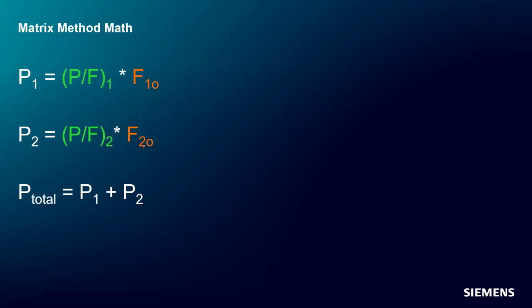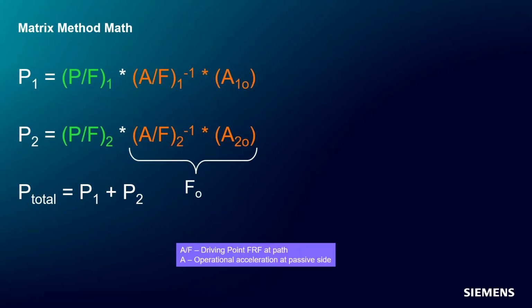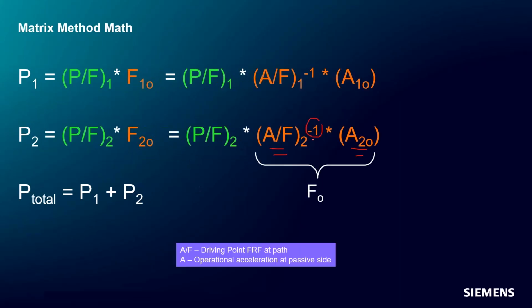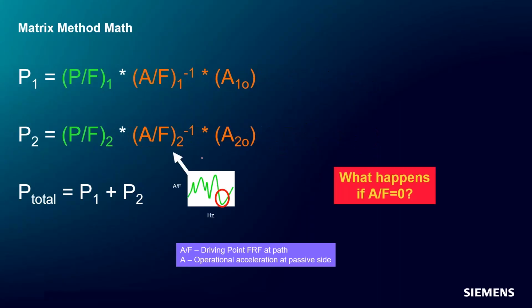There's another way to get the forces. You're using an FRF, a local FRF that you invert in order to do this. The only problem with this technique is an FRF could be close to 0 at an anti-resonance of a structure. If you invert something that's close to 0, what does happen there, Steph? You get a messed up matrix for sure. Yeah, you get infinity for your force, which I think is probably a little higher than what you actually have in real life.